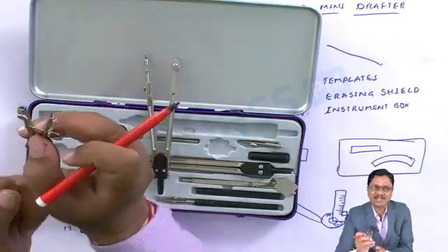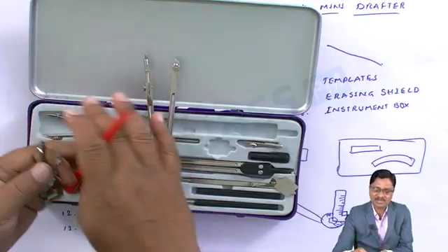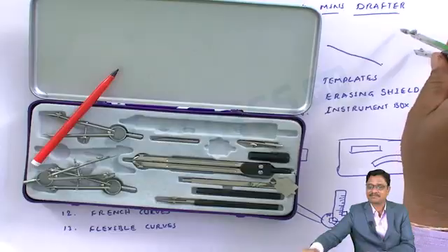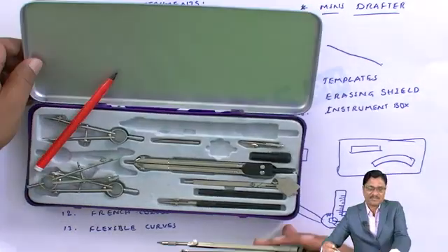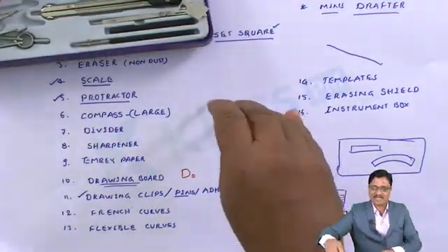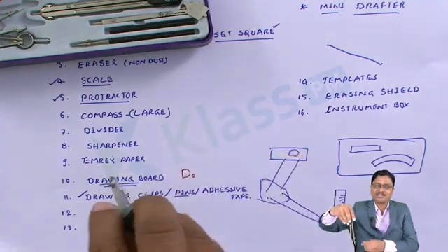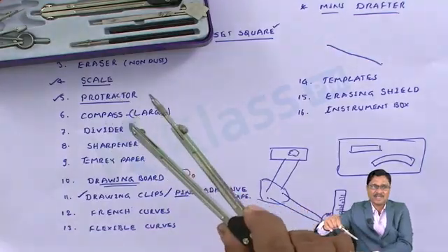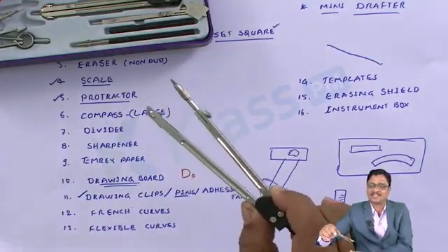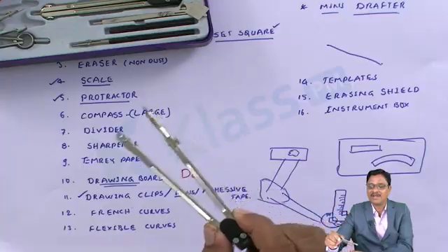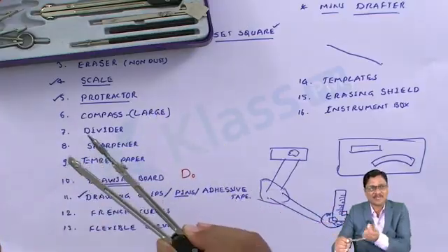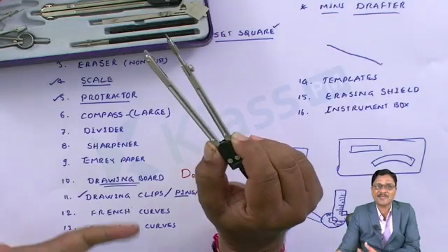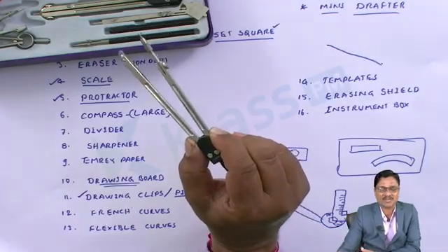This is used when you want to draw smaller circles repeatedly. So how are we able to draw with this one? By applying pressure, I can draw the circle like that. So while applying this, we are pressurizing here. While pressurizing, when you draw repeated circles, the pressure may unknowingly be disturbed, maybe by 2 to 3 mm differences. The 2 to 3 mm may cause us not to produce the accuracy the drawing intended.